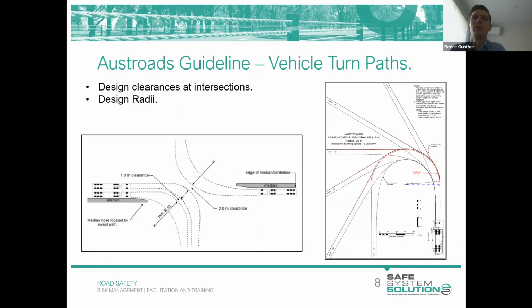Here we've got a snip of the Austroads Guide to Road Design that considers vehicle swept paths. To the right, just here, is a snip of a 19-metre semi performing a turn. It's important to note the red line associated with this diagram, as it refers to the radius of the outer wheel path, which is important for us to know when doing design vehicle checks.